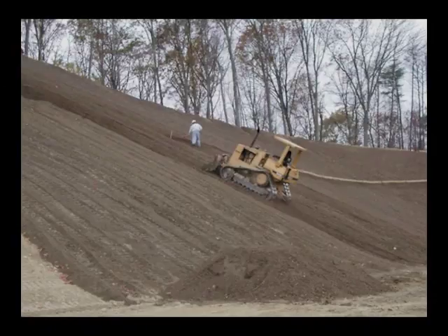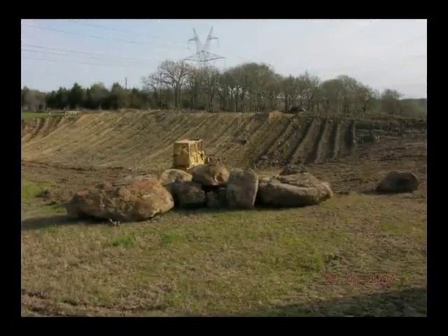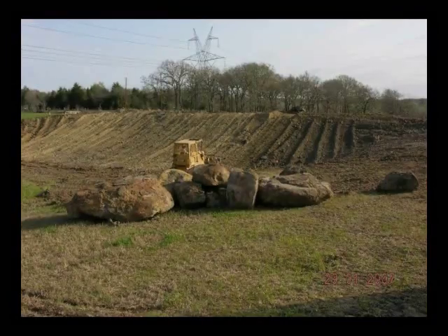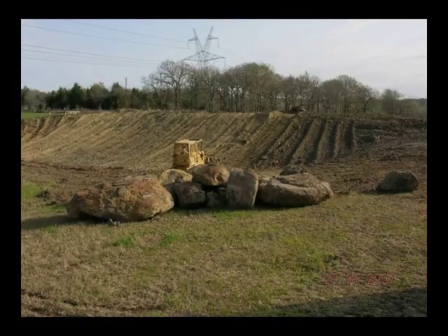Surface roughening or scarification is an erosion control practice. It involves the creation of horizontal grooves on the bare surface of newly graded slopes. The horizontal grooves reduce runoff velocity and erosion potential. Roughened slopes also help to establish vegetation by providing increased surface area for seed, mulch, and fertilizer, and by promoting moisture retention. Surface roughening can also be used without seed in areas of frequently changing grade.